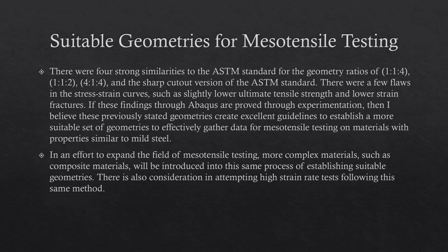fractures. If these findings through Abaqus are proved through experimentation, then I believe these previously stated geometries create excellent guidelines to establish a more suitable set of geometries to effectively gather data for mesotensile testing on materials with properties similar to mild steel. In an effort to expand the field of mesotensile testing, more complex materials, such as composite materials, will be introduced into the same process of establishing suitable geometries. There is also high consideration in attempting high strain rate tests following the same method.